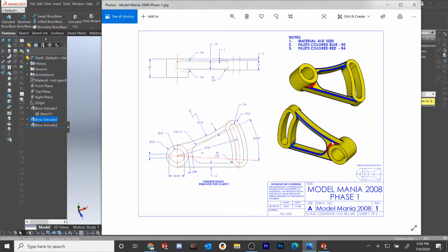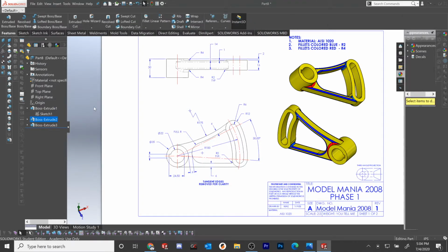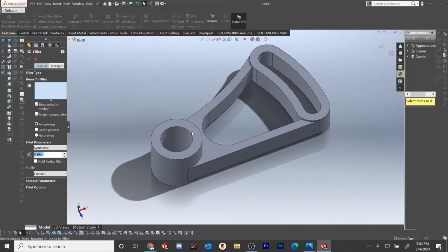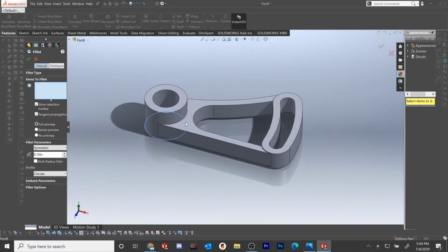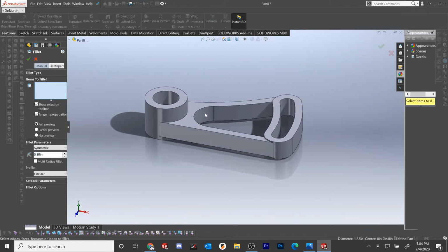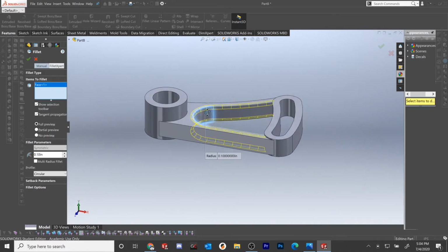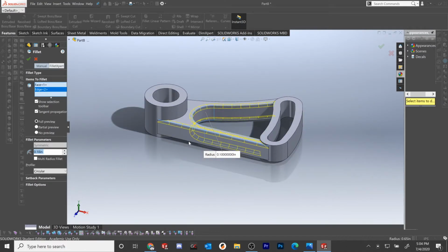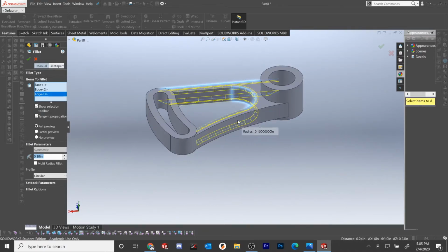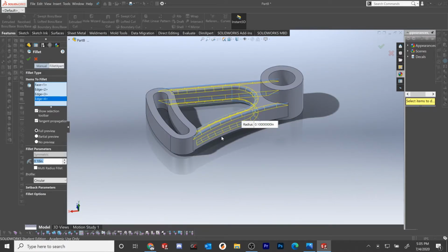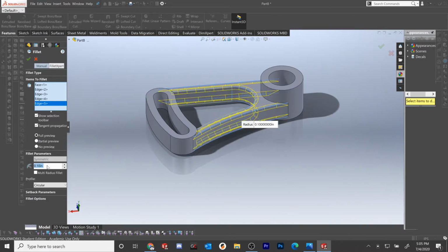I'm going to start with the blue fillets just because they cover more ground, and it looks like this red fillet here, you can see because it has multiple faces, it looks like this is added on after a certain fillet. So let's see how this goes. Let's see what order we have to put them in. I'm just going to select this face, whoops, this face, and these as well. Make sure I have them to the correct size, so 2 millimeters, there we go.